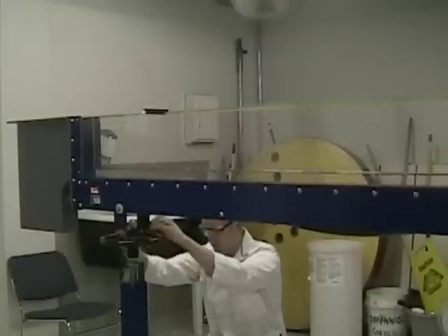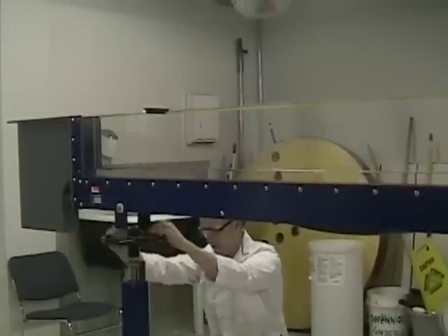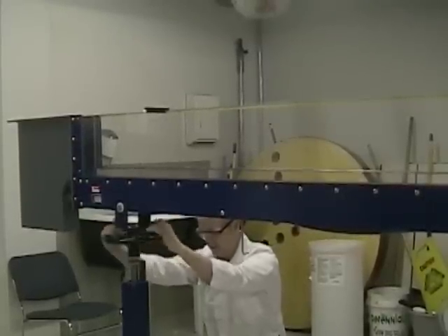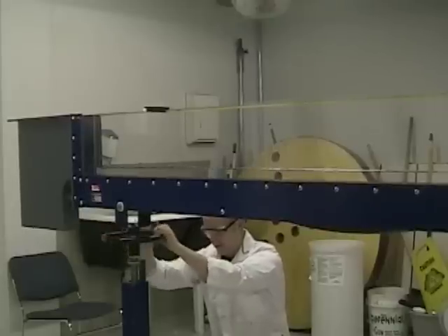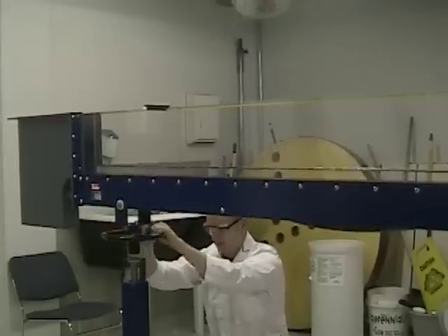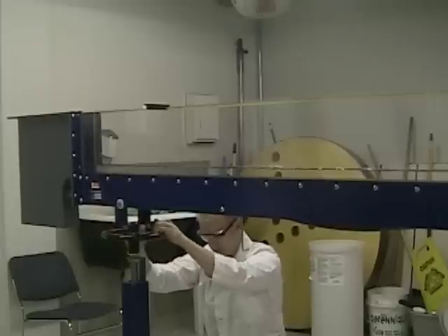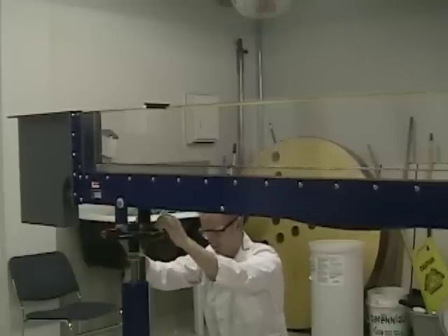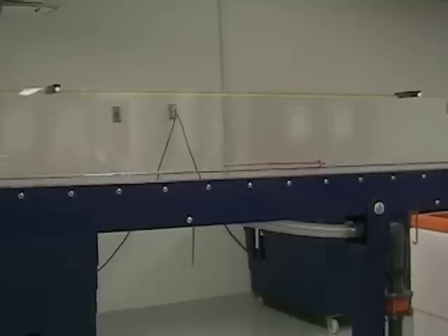We are going to increase the slope. Take a moment and decide whether the critical depth line should be raised, stay the same, or be lowered. You're right, the critical depth does not change since it is only dependent on the flow rate and geometry, and